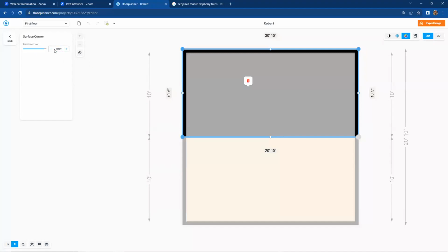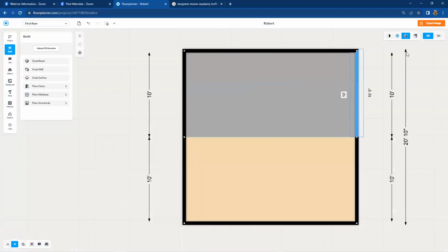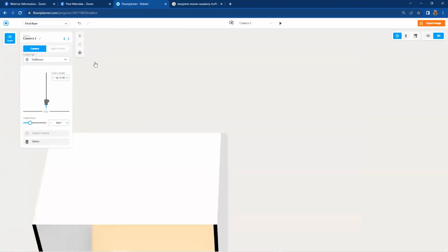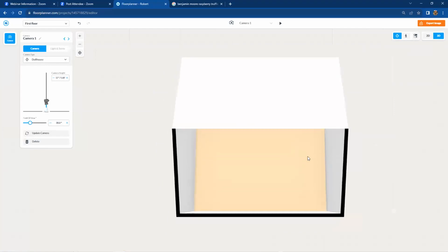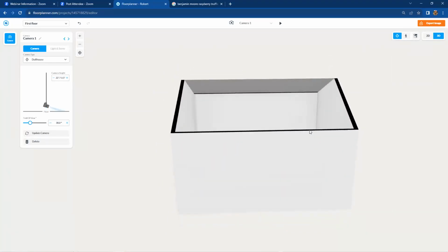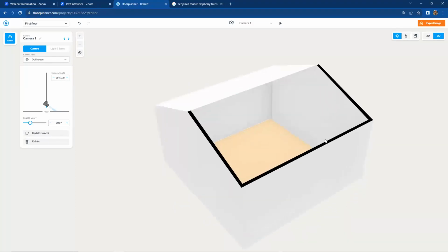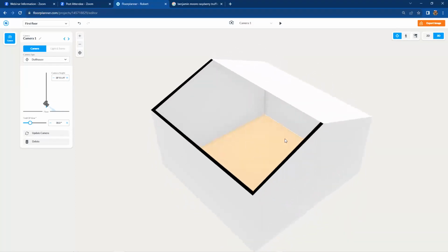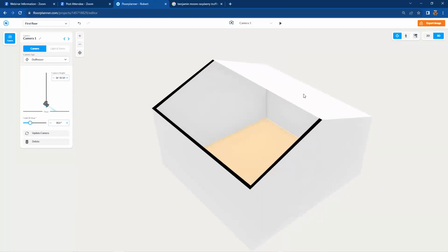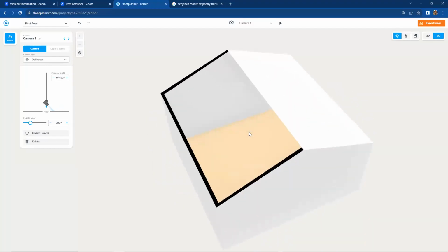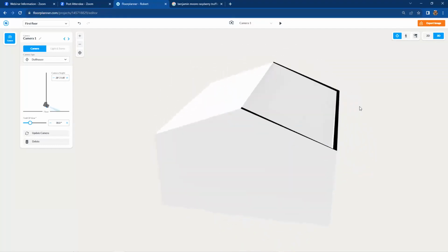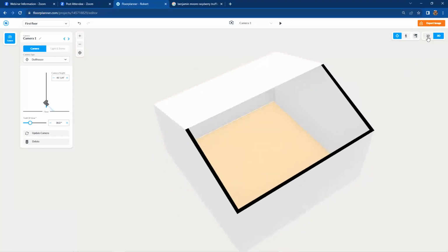Oops, not 1,000, just 14 feet, enter. And if I go back to 3D, see what we created, zoom extents, there's our ceiling, there's a roof, perfectly constructed, and we had full control to do it this time. This was not automated. And we can duplicate and rotate, or we could just trace out another one to finish out the other half. Cool thing about surfaces is that surfaces accept materials.